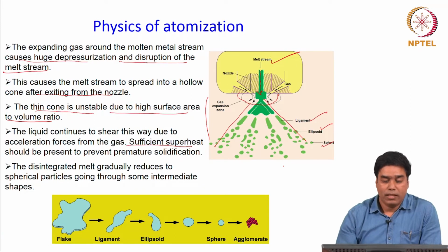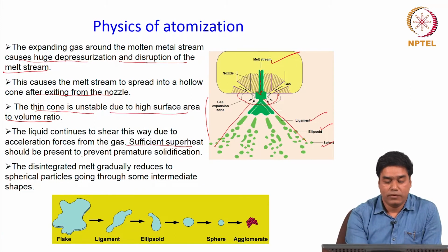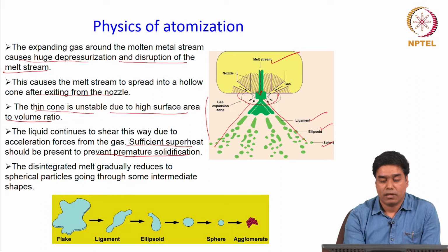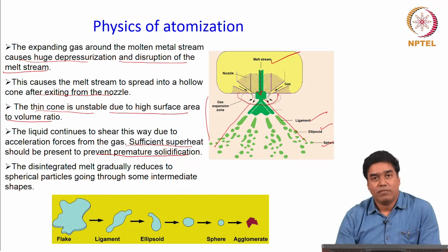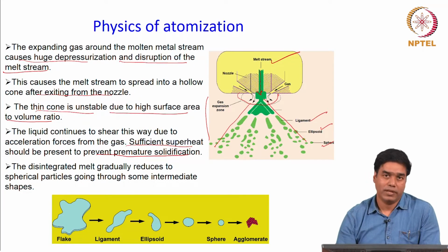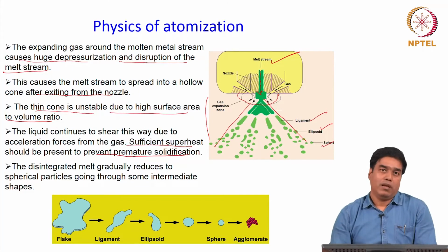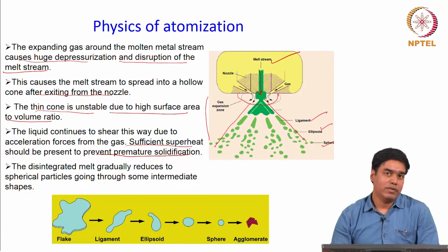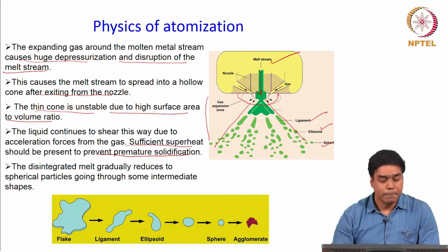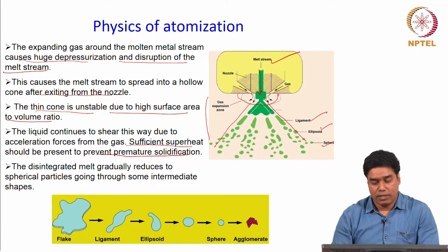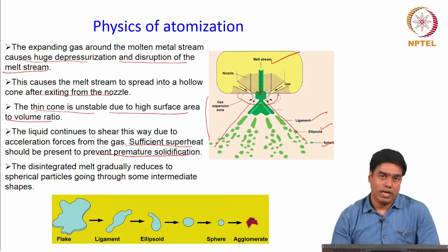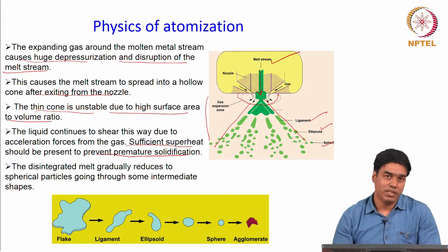Okay. Otherwise, it will suffer from premature solidification, and you may not have the kind of powder or particle morphology that you are looking for. Okay. So, that is why the melt should have sufficient superheat.